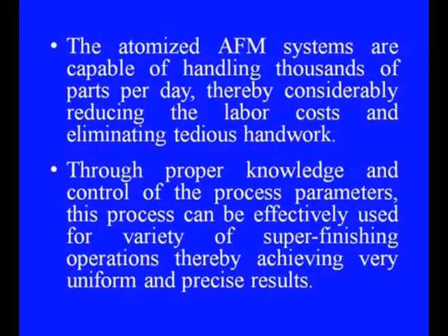The AFM process is widely used in a range of different finishing operations. At a given time, it can process a number of parts or different areas of the same workpart. Practical applications of this process could be in any of the situations wherein the media could be flown across. The automated AFM processes are capable of handling thousands of parts per day, thereby considerably reducing the labor cost and eliminating tedious handwork. Through proper knowledge and control of the process parameters, this process can be effectively used for a variety of super finishing operations, thereby achieving very uniform and precise results.